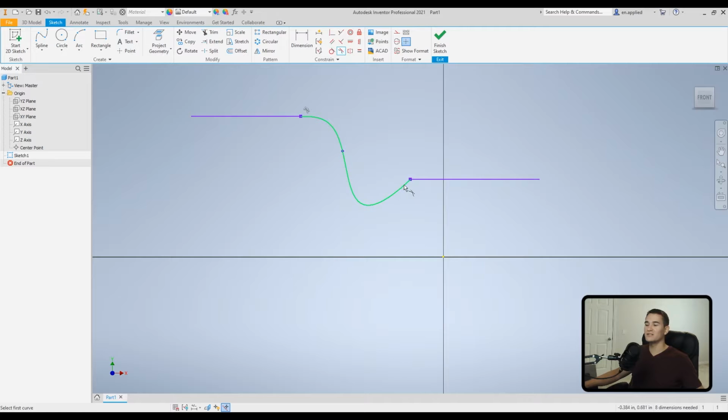But you'll notice down here, we're still going in at an odd angle with reference to this line. So we'll click on the curve and then click the line that we want to smooth it to. And there we go. It smooths out that spline to be in line at the endpoints with this geometry that was previously drawn up.